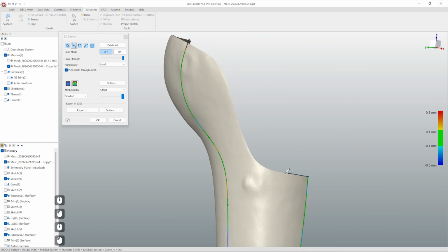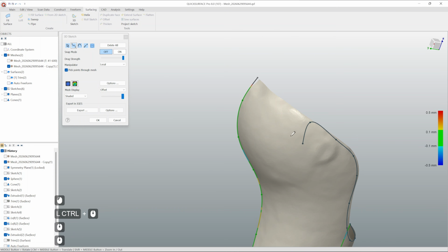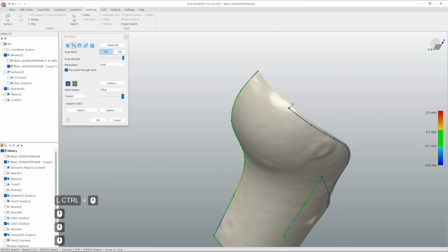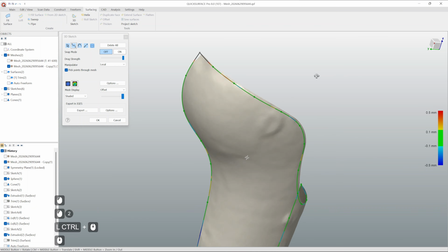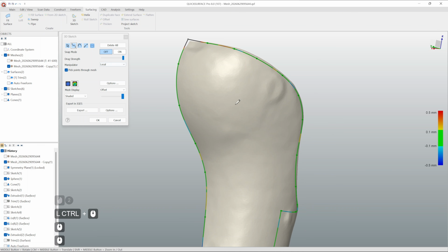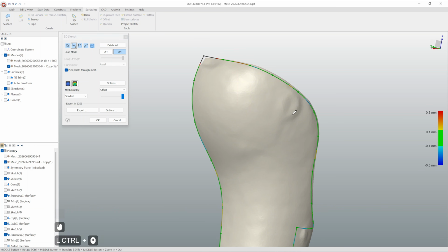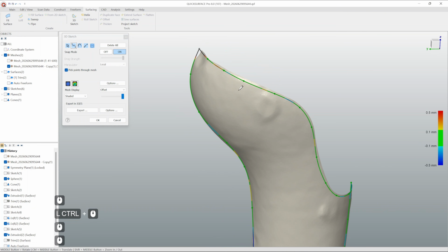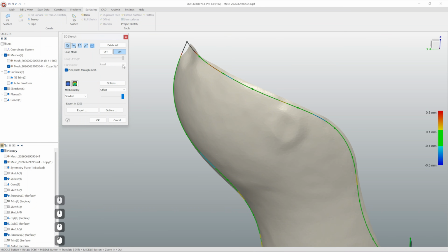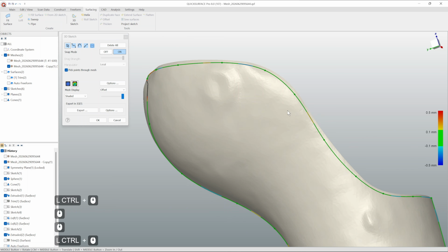Now I have to build curve here all around all this long and curved edge. So basically here thing is nearly the same as with freeform surface. The less control points you use, the smoother your surface will be. Not surface, in this case it's just a curve.